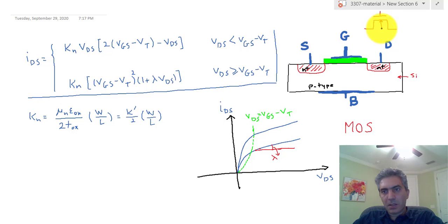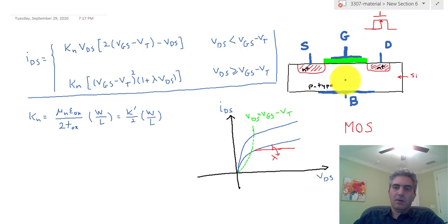So if I connect this to the terminal on the left, then that is always the source and the other one is the drain. And you can see the similarity between the symbol that is used and what's actually here. This shows you the capacitor and also tells you something very important: the gate does not generally draw any current because it's not electrically connected to the rest of the device. Rather, through this capacitance it only controls the current that passes through the drain and the source.